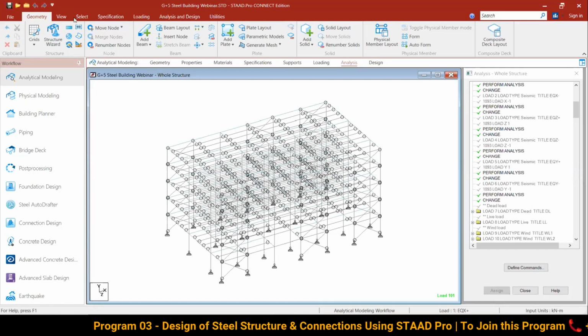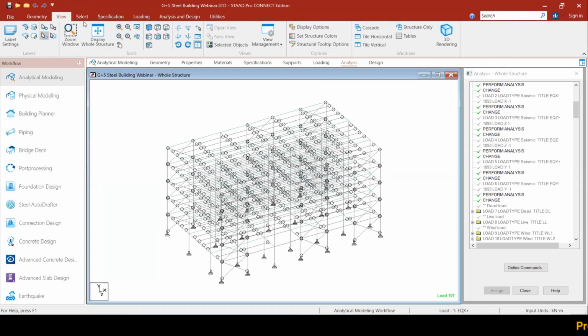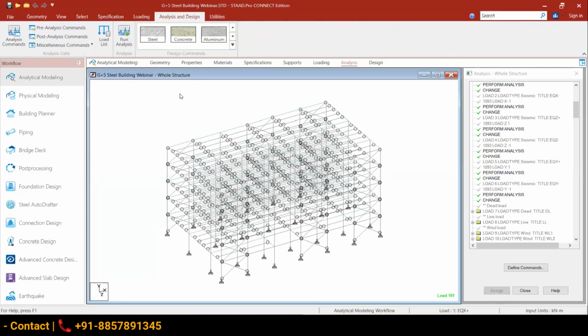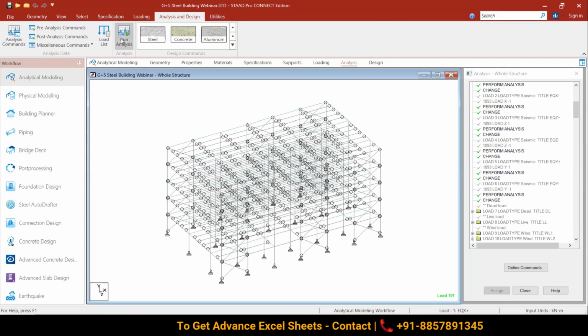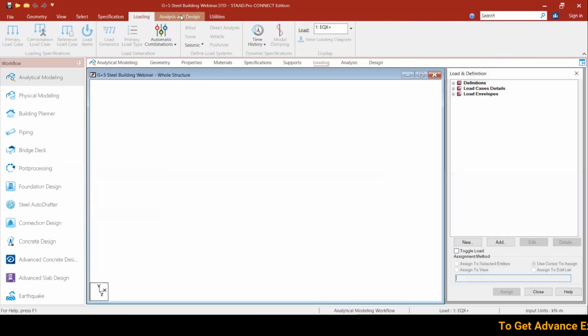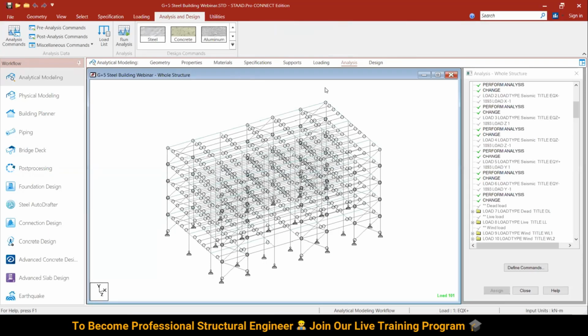We have 2 methods. If we apply by area load, then we don't have to mesh it. And if we are going with this plate, what we did right now, we need to mesh it. But right now I have not meshed it, and let's see. It could be that the load will be only transferred to the 4 nodes and not on the whole beam. Okay, I am not sure of that. Let me check it and we will get back to that question. For now, we are not sure whether it will be 4 noded or the load will be transferred properly. But let's proceed with this.